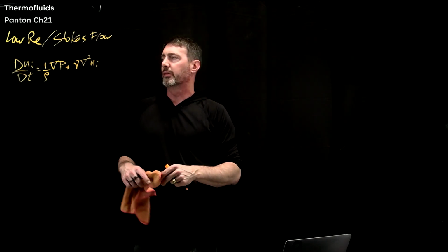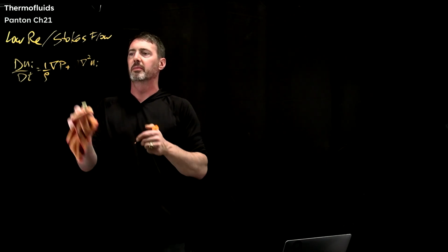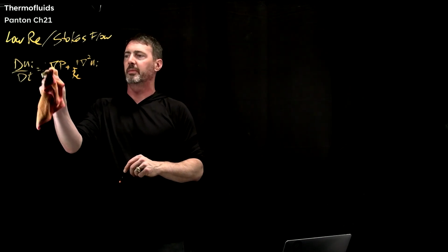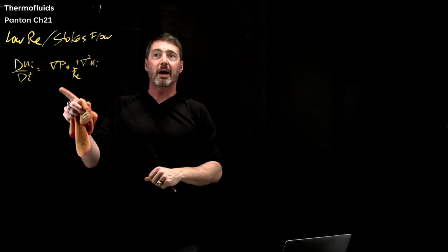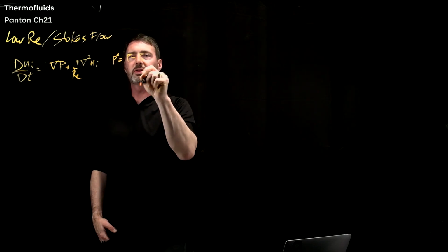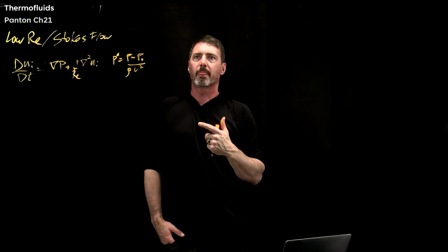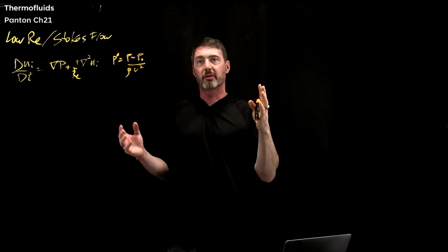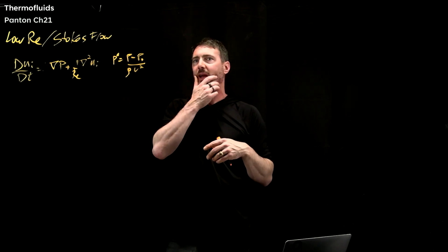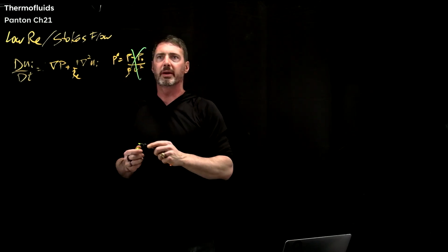Okay, and so when we non-dimensionalize this, remember that this term became 1 over Reynolds number, and this term became this. Now these are all non-dimensional. What was happening when we did that is we were non-dimensionalizing the pressure as pressure minus some reference, over rho times velocity squared. Well, when we slow things down, that's not appropriate, because things are slow. The dynamic pressure here is the wrong one. So this becomes the wrong thing to do. Put a big X through that.